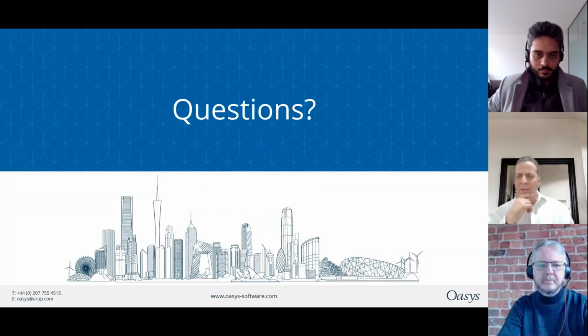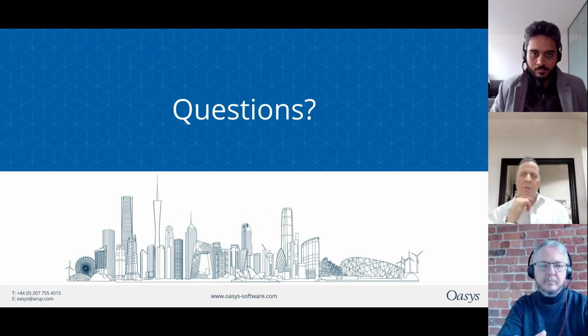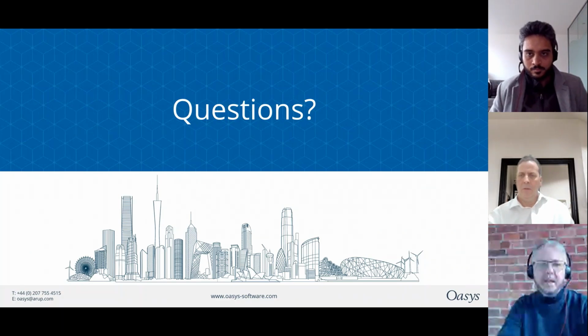Okay, great. The next one's concerning temperature analysis, Peter. So temperature analysis or thermal analysis, can that be carried out using GSA? Yeah, definitely. We have thermal loadings, which can either be a uniform load or cross-sectional thermal gradients. And obviously you've then got the coefficient of thermal expansivity set into each of the material grades. So yeah, it's all there. All there, quite comprehensive. Great.